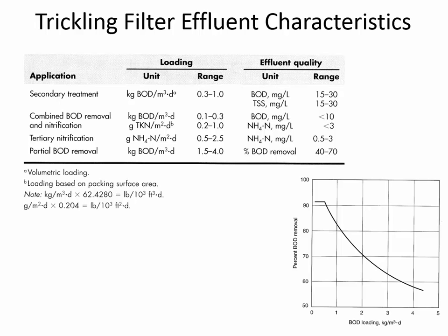The BOD in the water is being more completely removed because the bacteria at the bottom of the filter are basically desperate for substrate. It's not as easy for them just to use the simple carbohydrates that may be dissolved in solution, and so they'll break down every last bit of BOD that they possibly can at the low